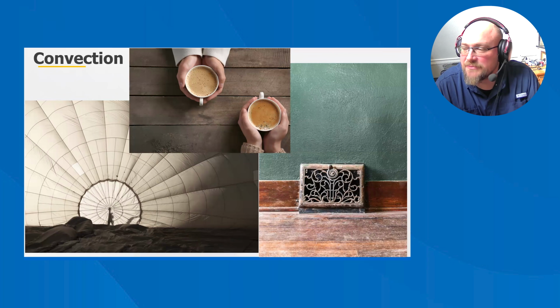In a gravity system, the warm air rises and cool air falls, and this is how the gravity warm air heating system circulates air. When a certain amount of air is heated up, it expands and takes up more space. In other words, hot air is less dense than cold air. Any substance that is less dense than the fluid, gas or liquid, of its surroundings will float. Hot air floats on cold air because it is less dense, just as a piece of wood floats because it is less dense than water.